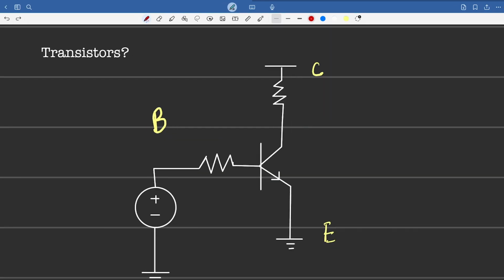So now we're going to talk about the second region, which is the saturation region. In the saturation region, we basically keep on increasing the base current, IB, and that causes an increase in the collector current, IC. So this is IB. Increasing this will increase or maximize the current over here. But there comes a point where an increase in base current does not increase the collector current, and that point is called the saturation point. So we are discussing the saturation point.